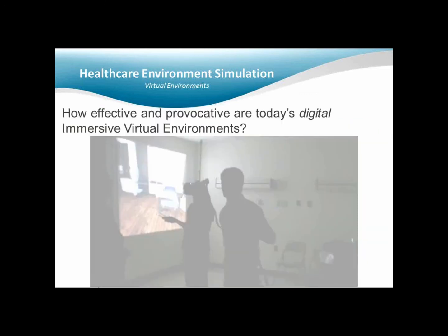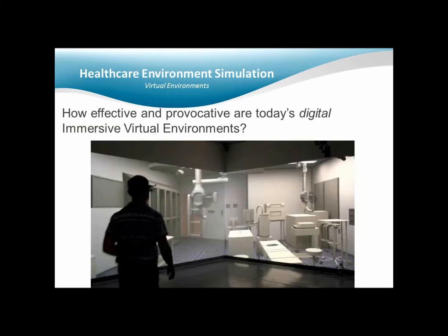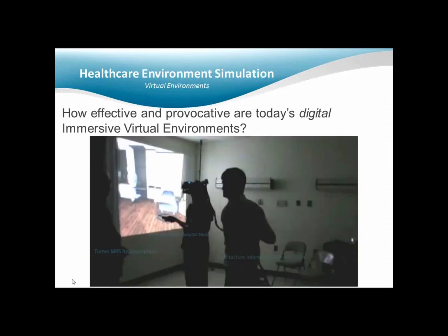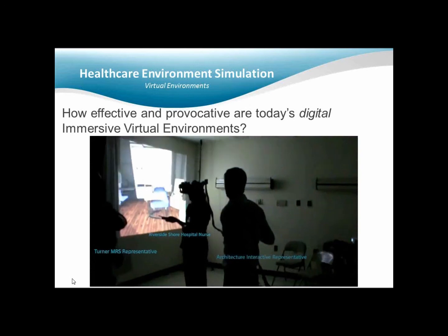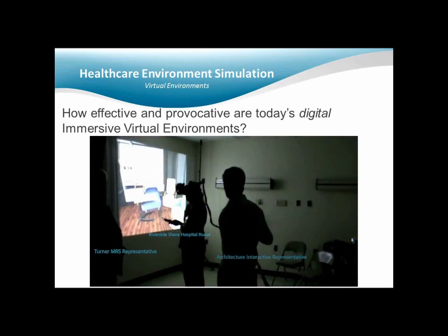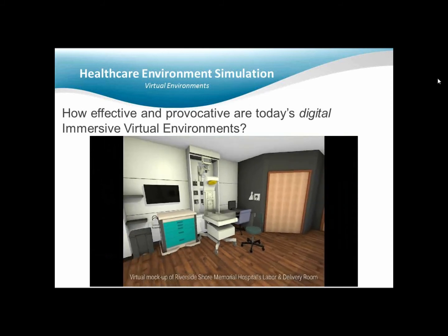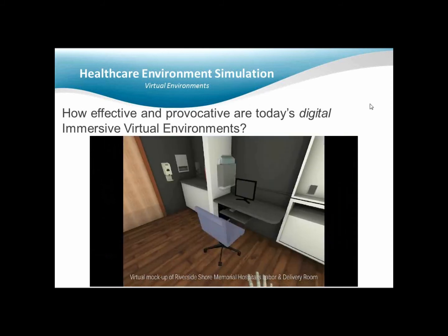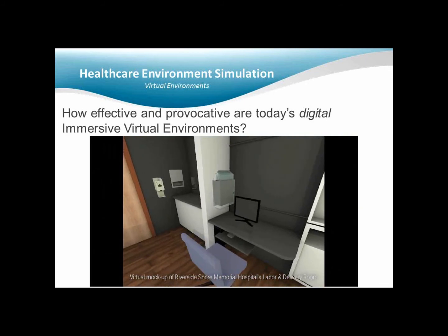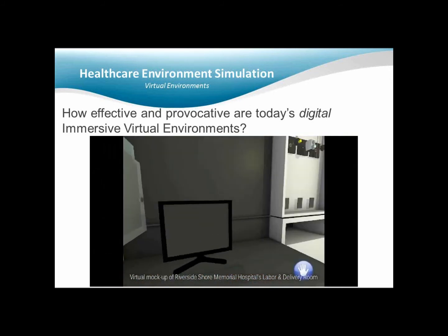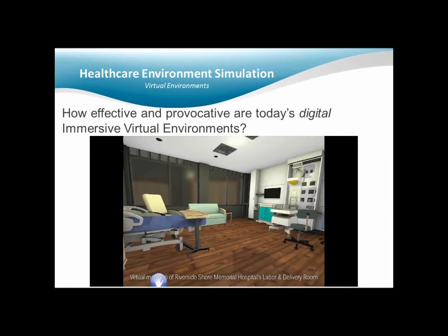So how does this translate directly into healthcare design presentation tools? These tools, again, allow you to put yourself in the location that's of interest to you. So here's a nurse in an actual designer view who's able to put herself at her charting station and see her lines of sight, see what she's able to see, what she's able to reach. The call button is just a little bit too high for everyone in this patient room, and being able to move it 12 inches is something you'd not necessarily ever catch on a floor plan or designer view.